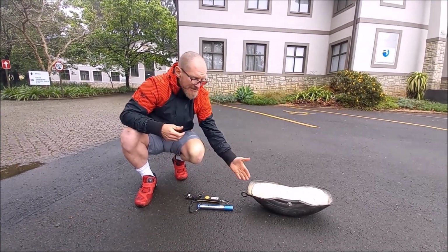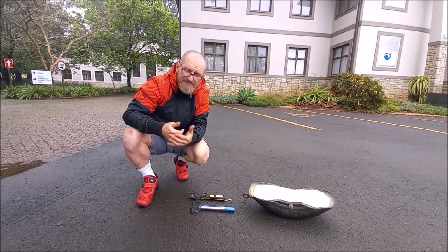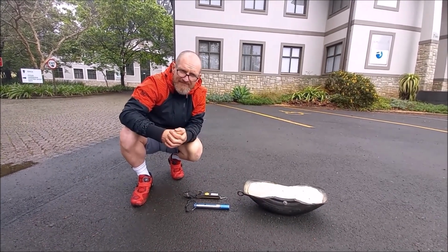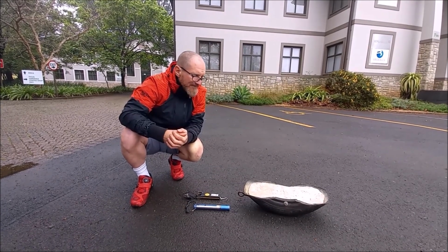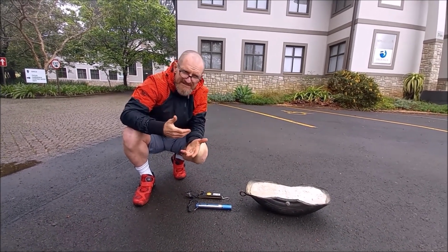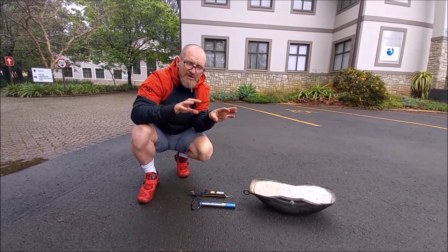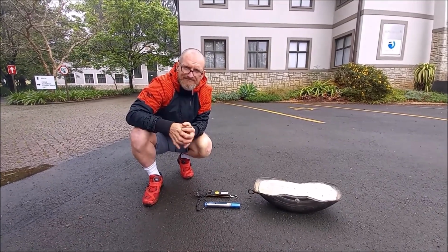Alright, so for the exact reason of trying to get a more accurate and reliable reading, generally we would take 3 pulls with one scale, 3 pulls with another scale, and 3 pulls with a third scale, and then across all 3 of those average that. That's for the process of repeatability. And then obviously once we do the skid test, and if we use electronic telemetry to do a further test, we would look at all of those individually and then average across all of them.